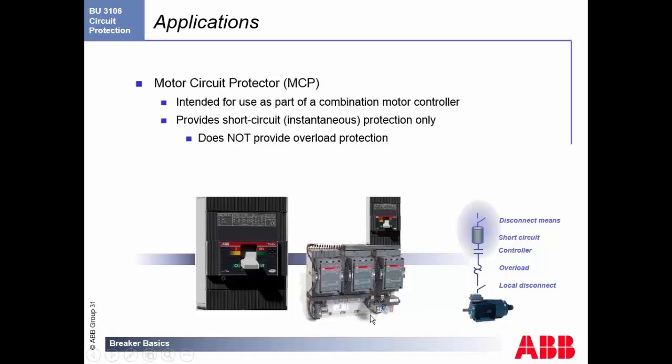Right below it, you have the actual controllers. These are the MCUs. Now we have several different types of motor controllers which allow you to do slow ramps, quick ramps, kick starts, all different profiles as far as what your motor requires, torque control, voltage control. So our controls are really, again, a topic for another webinar, but they allow you to comply with the NEC and, believe it or not, extend the life of your $40,000 motor.